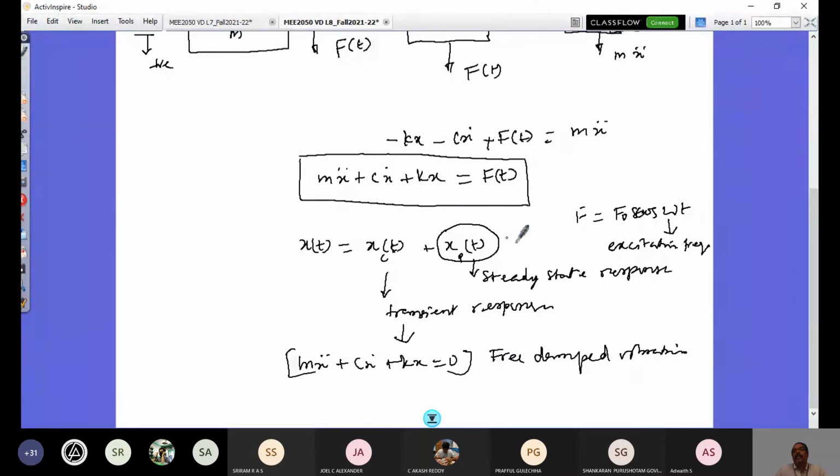The steady state response is going to be given by the response with this frequency. You could see with the natural damped free vibration that with omega d we had a response. We looked at that so far, and this is the response. This you should understand first. The addition of these two is my total response of the forced response system. However, I would ignore the transient response in the functional aspect of vibration, and make my system vibrate with the steady state response.